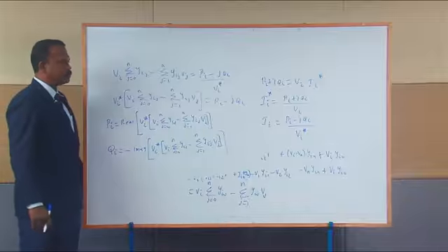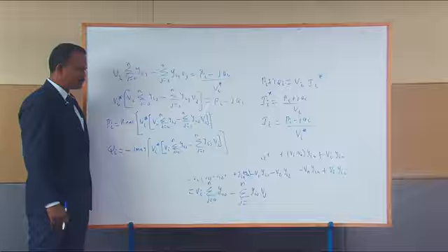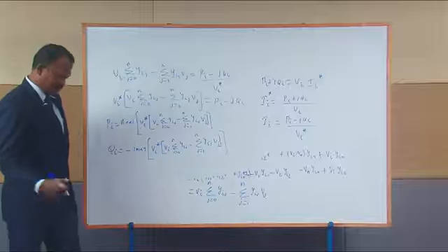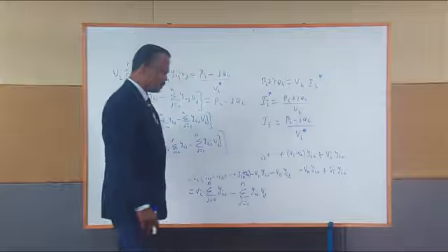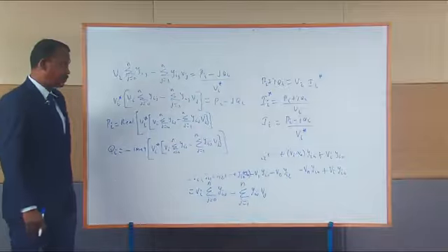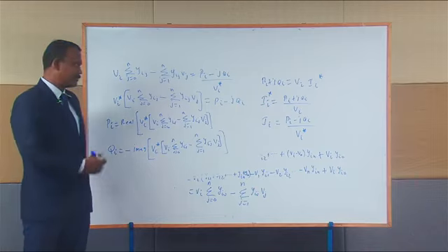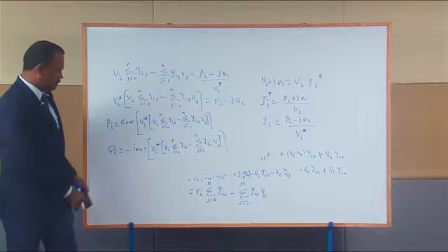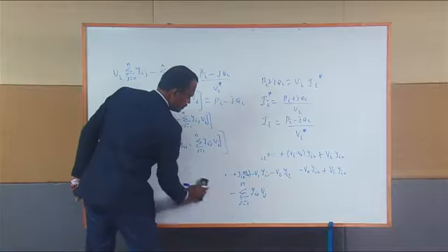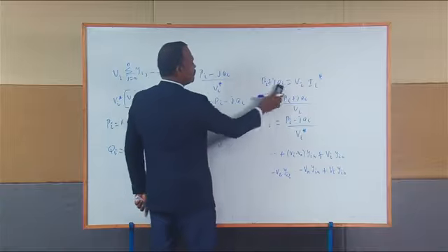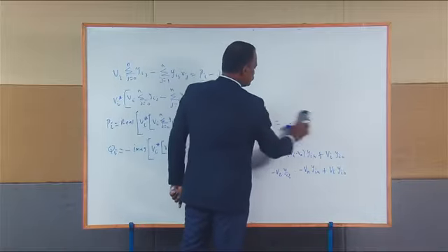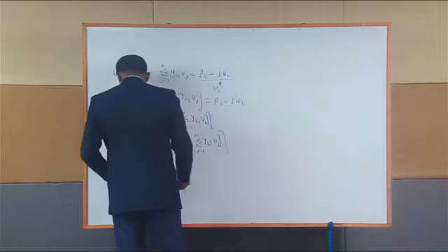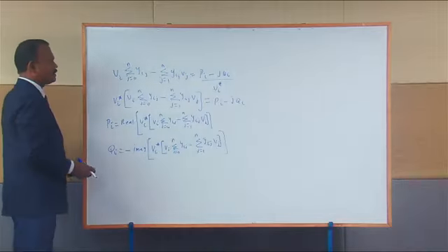If you want to find the solution for the power flow equations, we can use this form of equation, or methods like Newton Raphson use polar based equations. Then you need to convert the same equations into polar. So this is a very simple power flow equation. If you want to get the solution for the power flow problems, we need to solve these power flow equations.